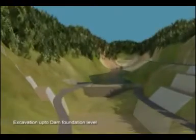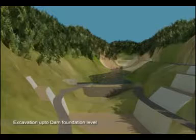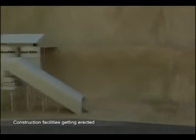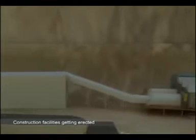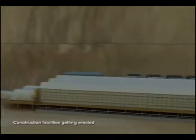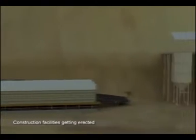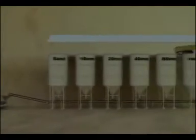Water between the coffer dams is pumped out to expose the river bed. Further excavation is now carried out up to the dam foundation level. Simultaneously, tower crane, batching plant, wet belt and other construction facilities are erected at appropriate locations. Let us now understand in detail the trajectory of material movement involved in the process of building the dam structure.